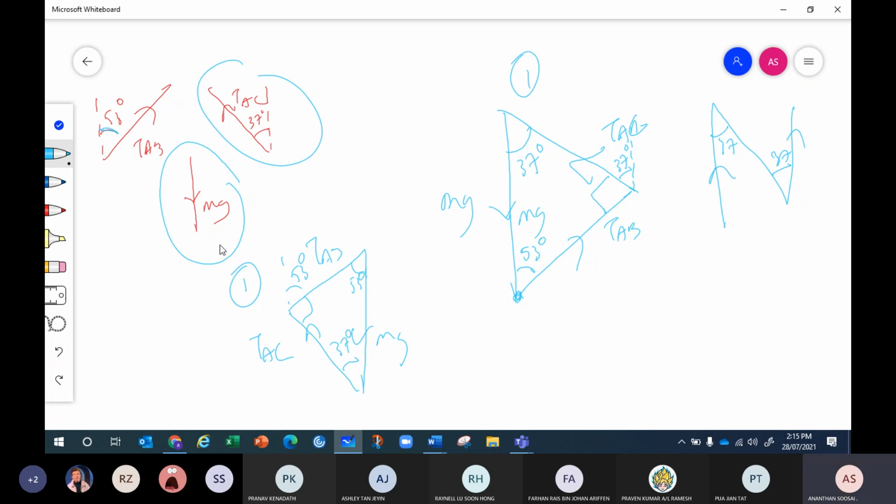My advice, get all the three vectors with their angles. The angle must be from vertical or horizontal. Start to draw the triangle by using the vector with perfectly vertical and horizontal first. You've got one vertical, another one horizontal, another one diagonal. Best is take the vertical first, draw the first one, then draw the horizontal one, then finally you take the diagonal to make the triangle.